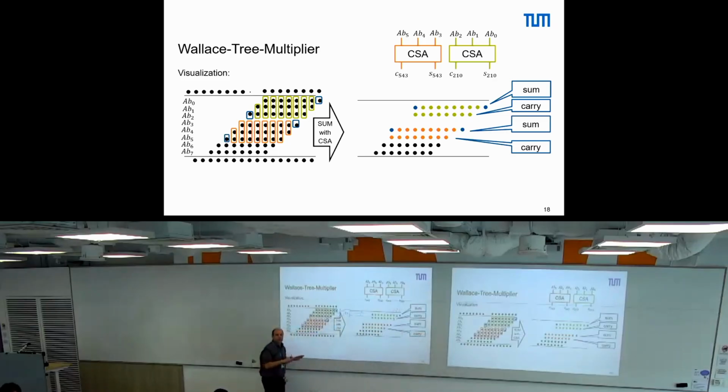Which values precisely come out doesn't really matter. I only want to know what I need structure-wise for the carry save adder. So this one here is the right one. This one here is effectively the left one. It's exactly the same. So this bit here goes directly out, this bit here goes directly out, and the rest is always computed with a sum and carry bit. Okay.